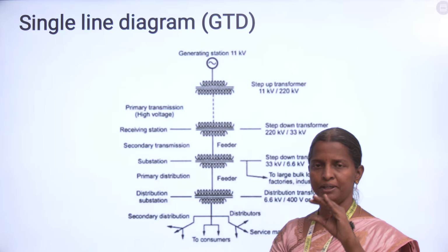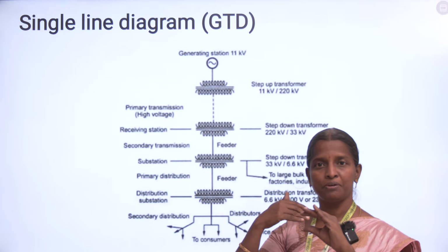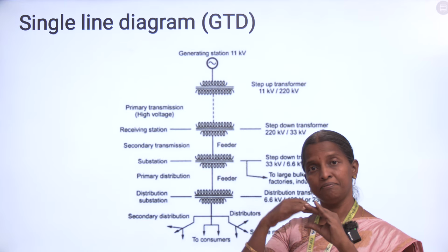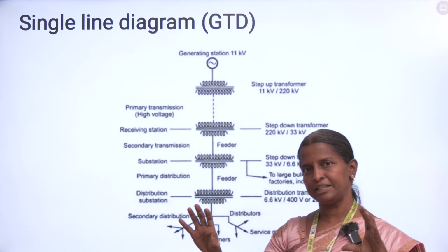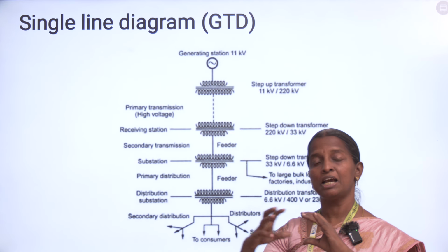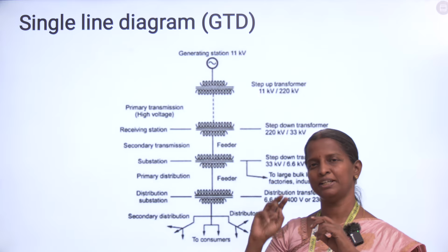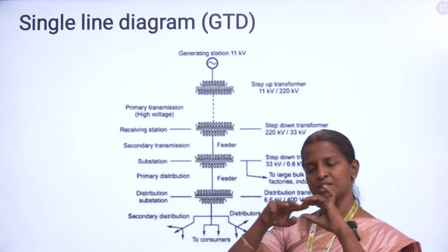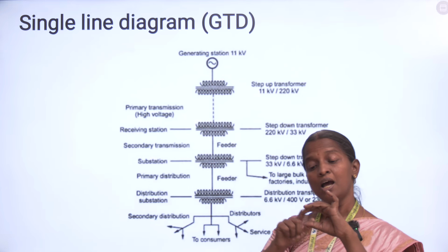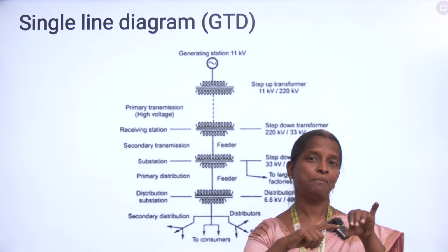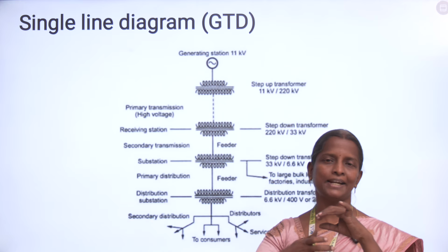That is, we take a bobbin, we wind the primary coils, after that we put the insulation. Next, on that bobbin we wind the secondary winding, and again we put the SI tape because it has to be physically separated. And the next thing is to insert the iron core. That iron core may be of I type or E type, so many types are there. If this is a bobbin, you have to insert this. If this is a hole, you insert the E core here, and opposite you insert the E core, but here there will be some gap. In that you have to fill the I core. So now it will form a transformer.